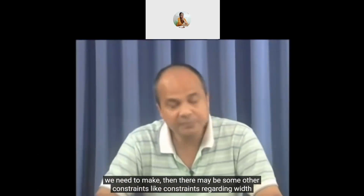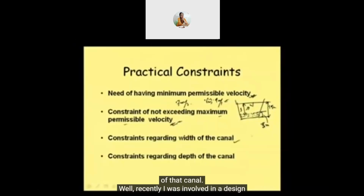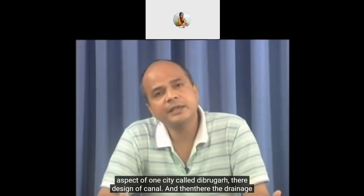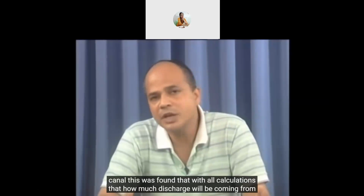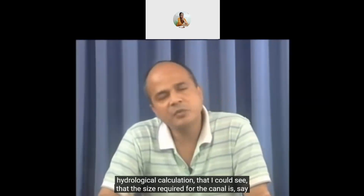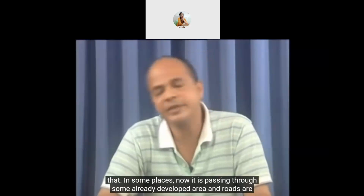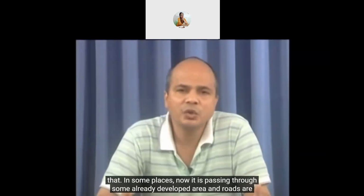Then there may be some other constraints, like constraints regarding the width of the canal. Recently I was involved in the design of a drainage canal for one city called Dibrugarh. With all the calculations, of how much discharge would be coming from the hydrological calculation, I could see that the size required for the canal, if I go for the best hydraulic section, the width becomes 4 meter, 5 meter like that in some places. Now it is passing through some already developed area and roads are there.